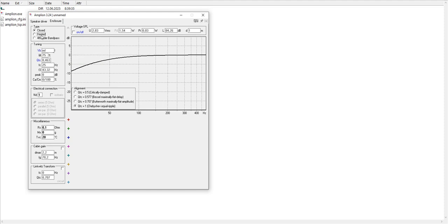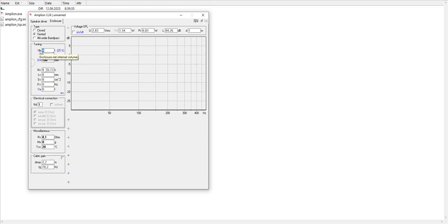In a vented, ported box, you define the volume, amount of damping material, and system resonance frequency. Clicking on AC or double-clicking on the graph is a quick starting point. By clicking on DV, you can estimate a suitable vent diameter for low-noise performance.